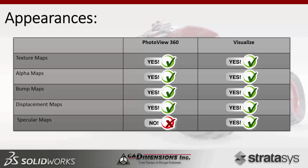Now, a texture map, you can apply sort of like a bitmap image, and you can apply that to a face. Alpha map will allow you to actually map holes into the appearance, so you'll be able to see through the appearance. PhotoView360 does it a little bit different than Visualize, but in either software you can get this accomplished.